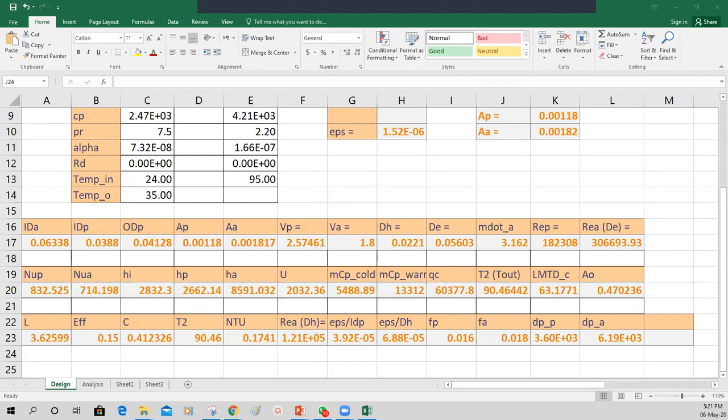First of all, you have a certain flow rate, which is m dot, and you have to increase the temperature. So you're multiplying by Cp, and then you are increasing the temperature, let's say from T1 to T2. So when you calculate this, it comes out to be in watts. The unit will be watt, right?